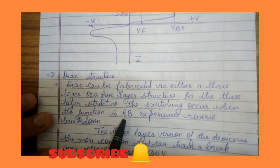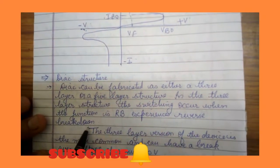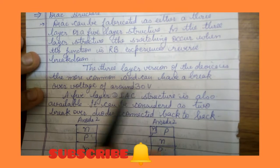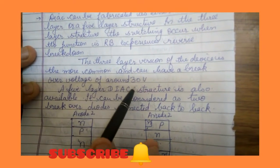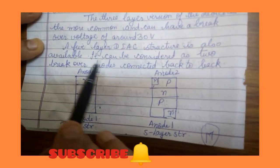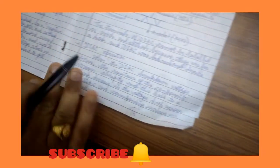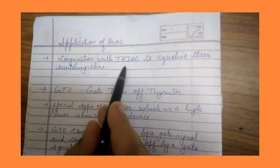In the 3-layer structure, the switching occurs when the junction is reverse biased and experiences reverse breakdown, as shown in this figure. The 3-layer version of the device is the more common and can have a breakover voltage of around 30 volts. A 5-layer structure, shown in the figure, is also available, but it can be considered as two breakover diodes connected back to back. Application of the diac: it is used to utilize its switching characteristic with the triac.